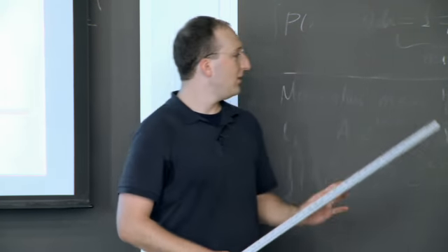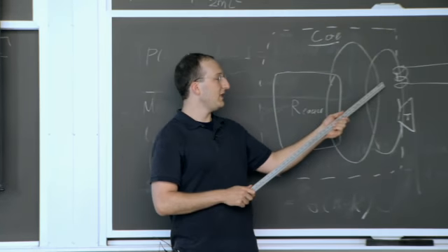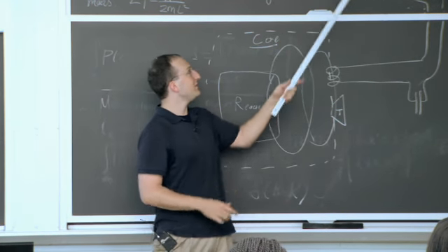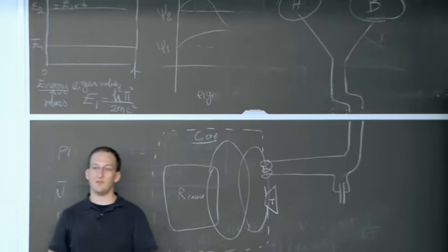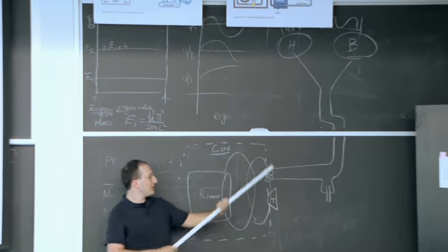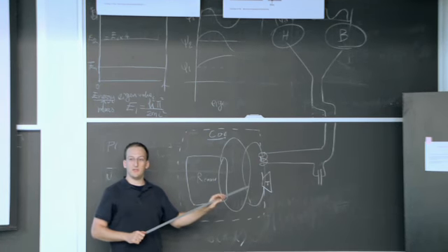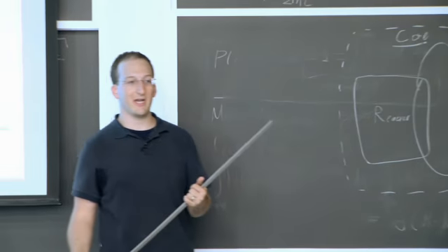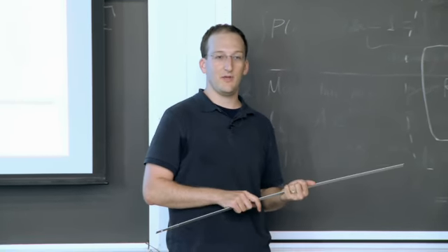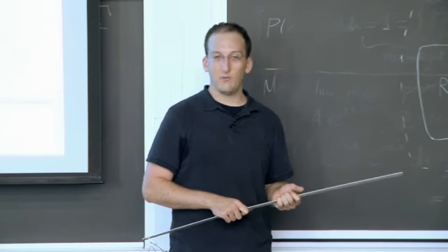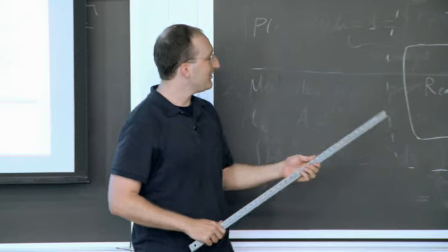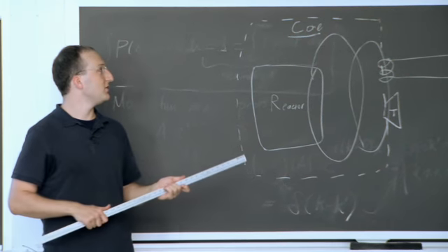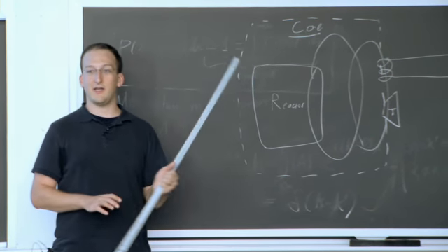So you've got to consider what temperature the core is giving you heat at, and so what temperature the heat can come out of the heat exchanger. By the time it reaches the processing plants, what temperature is your working fluid now? What temperature is it when it's coming back? Is it too cold? Is it too hot? Is it just right? What are the flow rates, and what are the implications? If you jack up the flow rate, does the pressure drop go up? Does it become harder and harder to pump things? And what happens during transients? So if all of a sudden the cooling fluid heats up a little bit, do you have any materials concerns or concerns that'll propagate down the line and affect any of these other groups?